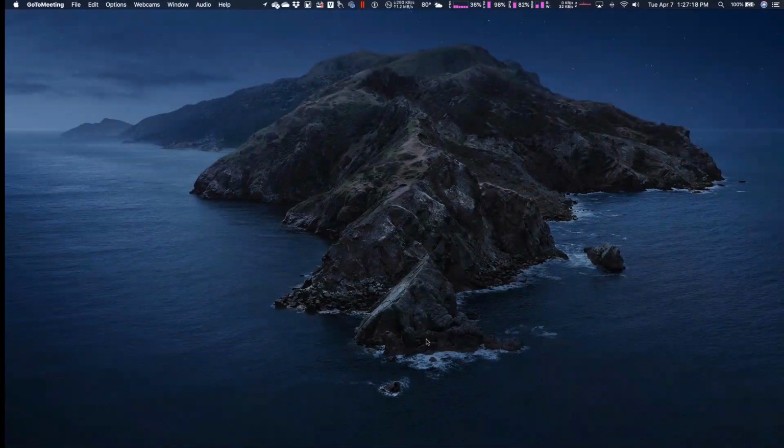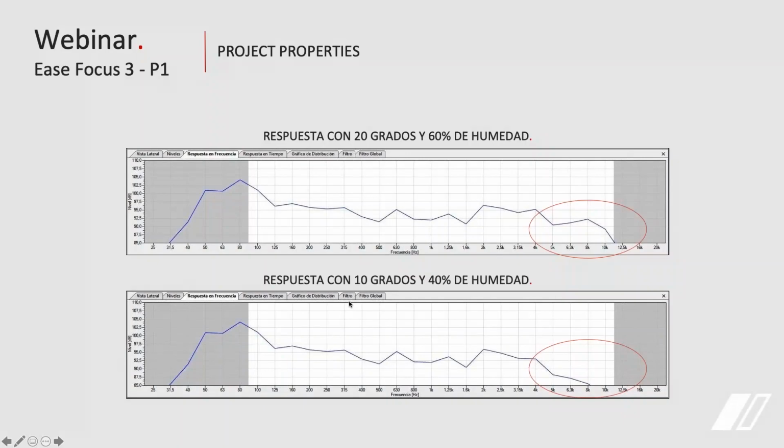The reason that happens is how the temperature works. Higher frequencies, hotter with more humidity, gives us more particles out in the air, which gives our high frequencies something to travel through a lot easier. When we drop it 10 degrees and take away the humidity, there are fewer particles in the air, and there's less energy in the air because of temperature. It's colder, thus our high frequencies don't go as far a distance.